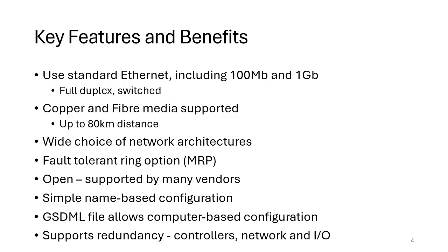Another aspect of PROFINET that's good is it does support redundancy. Depending which level of system redundancy and cable redundancy you use, you can have redundant controllers, hot standby PLCs, you can have redundant network cables, mainly using MRP, and you can have redundant I/O devices, and you can mix and match that redundancy so you can have very high levels of fault tolerance. So very good for redundant applications as well as simplex applications.